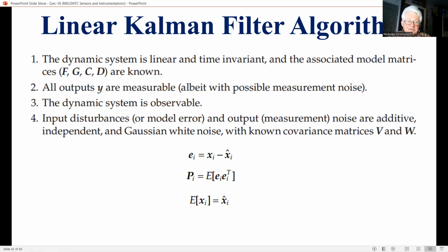The Kalman filter is an optimal estimator tool where the unknown variables, the state vector, are estimated by minimizing the error covariance of the estimate, given the measured data, as time goes to infinity.